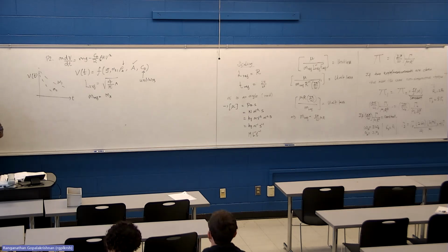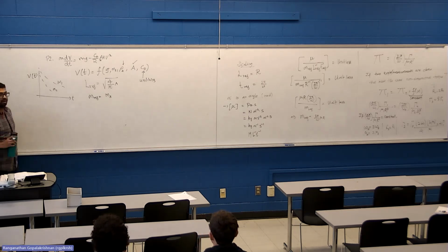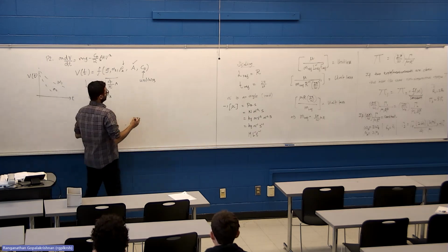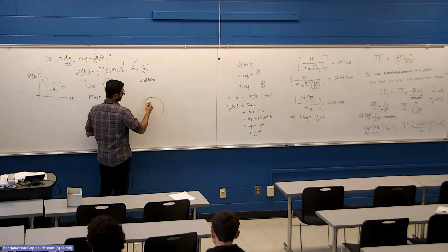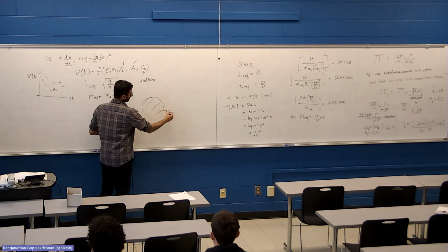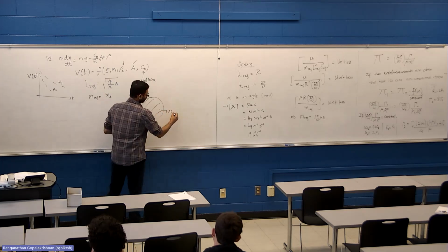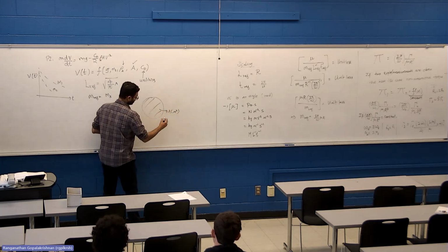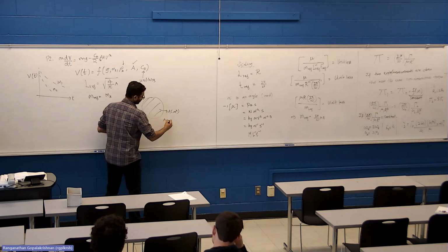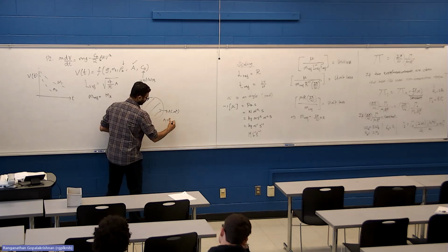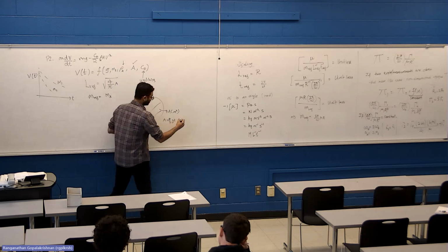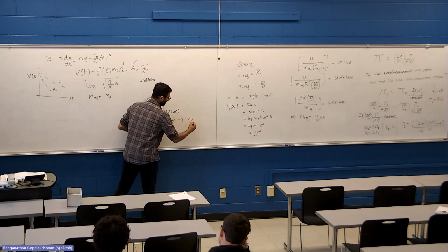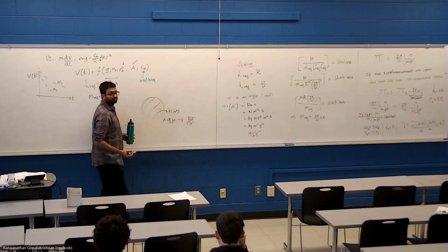In your L reference, why did we do the square root of 4A over pi? If they are telling us this is a sphere and it has a surface area A, which has units of meter squared, so I am considering if it's a sphere, A equal to pi by 4 D squared. So if I want a length, a convenient length to think about is the square root of 4A by pi.